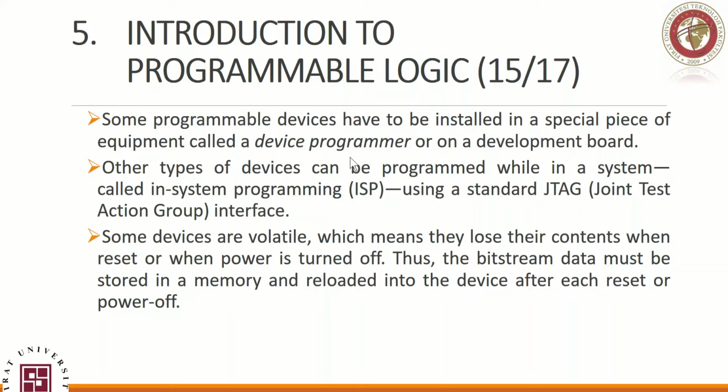You don't need to go into them, but there are ways to program based on the device itself. In order for you to install what you create as a design, you need to know your PLD or FPGA, the programmable logic device you are using, and what fits it. You need to use ISP, JTAG, or a development board or anything relevant to that. It depends on the device that you are programming.